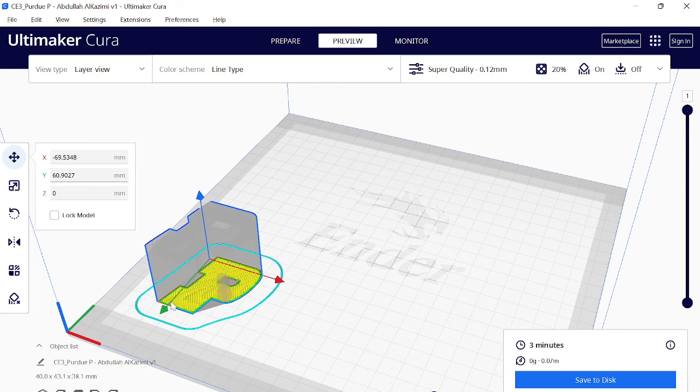So that's what we want to see from you guys on the slice image. Just import it in, scale it down to the right size, try to find the most stable way to print it and orient it that way, and then send us a screenshot just like this of the slice. We want to see all the colors, right? The colors tell us the different patterns and how it's going to be printing. Are there any questions on this slicing component of the project?